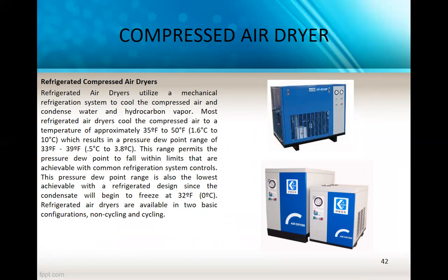Most refrigerated air dryers cool the compressed air to a temperature of approximately 35 Fahrenheit to 50 Fahrenheit, 1.6 C to 10 C, which results in a pressure dew point range of 33 Fahrenheit to 39 Fahrenheit.